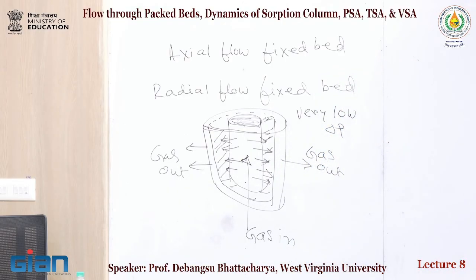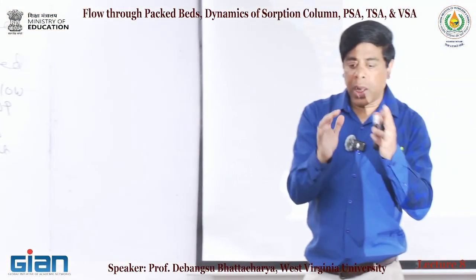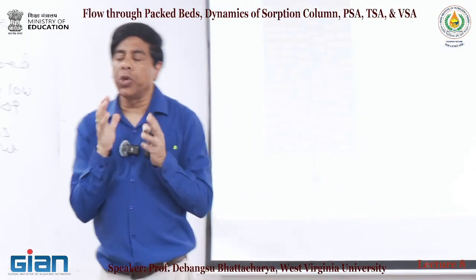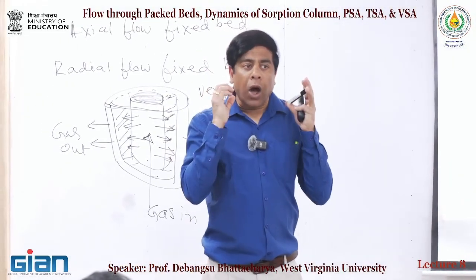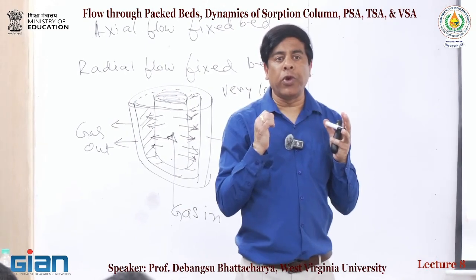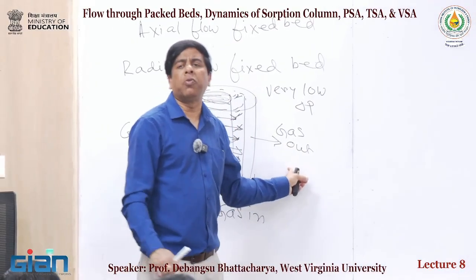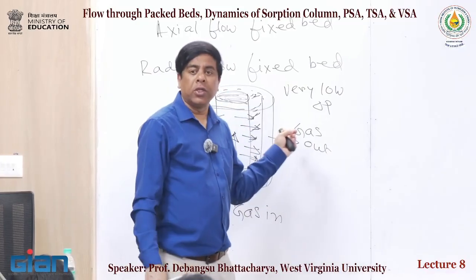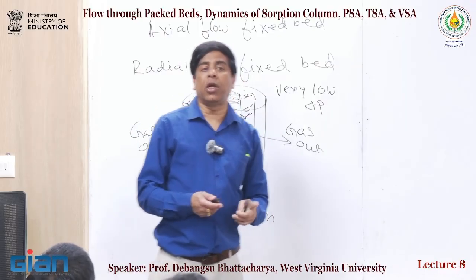So as Dr. Sathuraman was saying, we have to keep in mind that there is a blower as part of it. If I'm doing a power plant capture, we have a blower there, and how much pressure drop is needed for flowing through these. So this type of bed is actually very nice for that. Pressure drop is almost zero, negligible, compared to the same type of bed. So this is a criterion that you have to keep in mind.